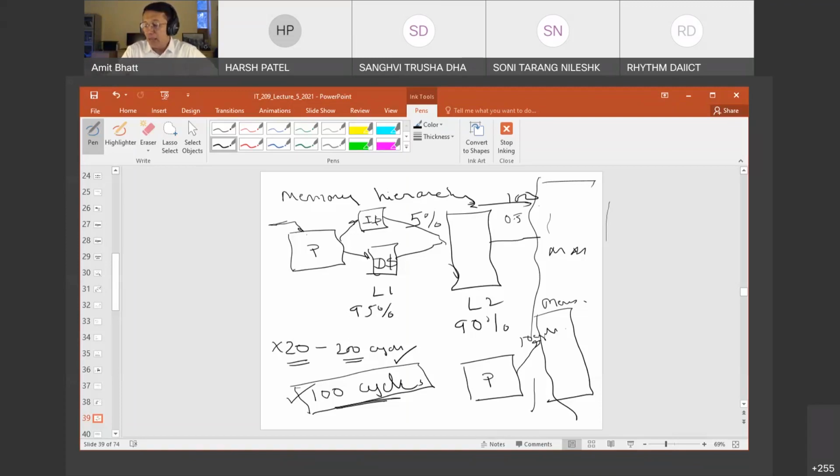I mean, the processor may hang. In a general purpose processor, there are more chances of hanging, because the processor designer doesn't know what kind of program would be thrown at it. Someone may write a program which suddenly creates a resource crunch. That means a structural hazard, where 2 instructions at a time are trying to access a particular thing. Then the processor would hang for a while, or one instruction will have to wait till the other finishes.